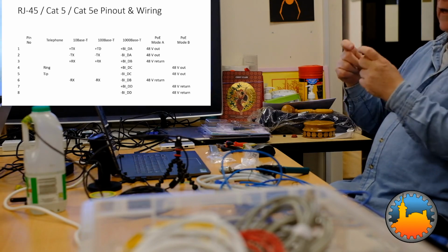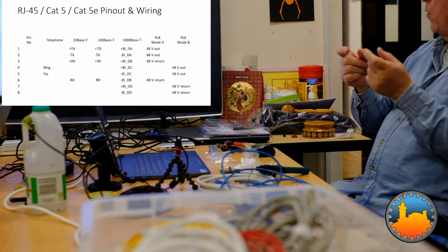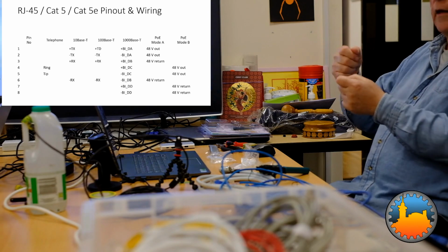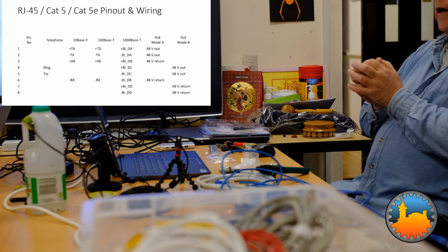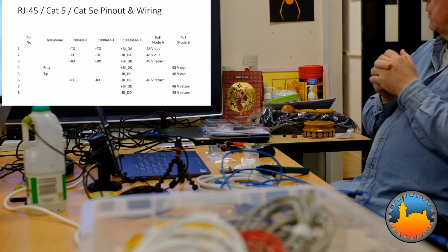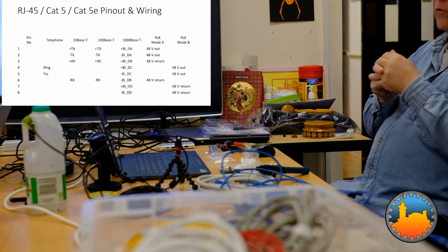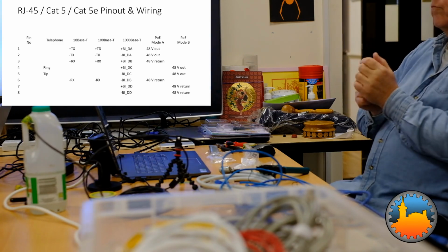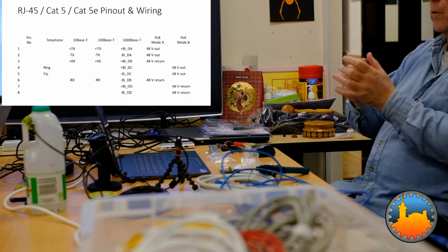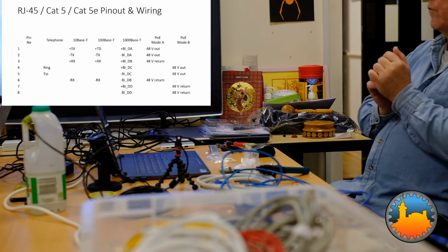So you can now buy a little board for a Raspberry Pi, a power over Ethernet or PoE board, which you can put onto your Raspberry Pi and then feed the power down the spare two pairs. That's done at 48 volts, and the little board steps it down to whatever the equipment at the other end needs. So if it's a Raspberry Pi, it will need 5 volts. There's a little converter that will do it for you.